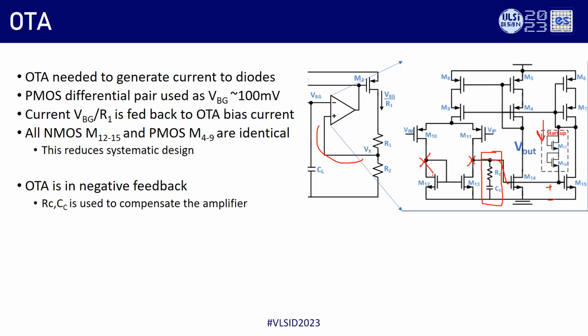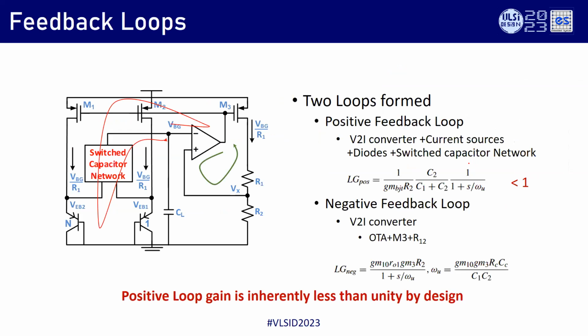But in that case, this node, this node and this node differ by a few millivolts. Ideally, they have to be exactly the same. That turns into a systematic offset. Now with this shallow bias, those two will be almost the same. We have seen a few tens of microvolts, whereas with fixed bias it could even go to a millivolt. The issue is not 1 millivolt or 10 microvolts, but the temperature drift, which we can show you clearly on the DC characteristics.